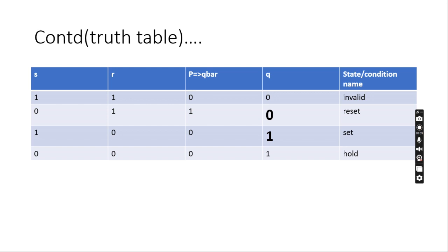If we want to make it valid or useful, we should change any one input. Whenever the inputs are 0 0, even if we feed back the output many times, it will maintain the same output. We cannot go to a valid state from the invalid.